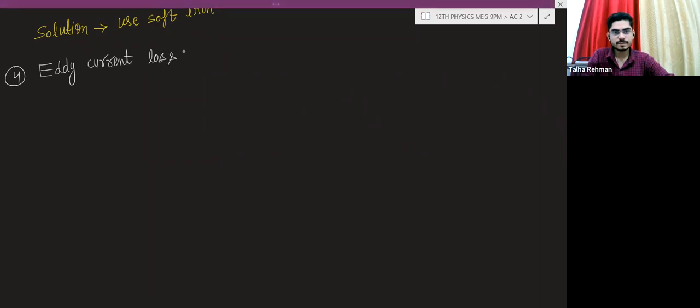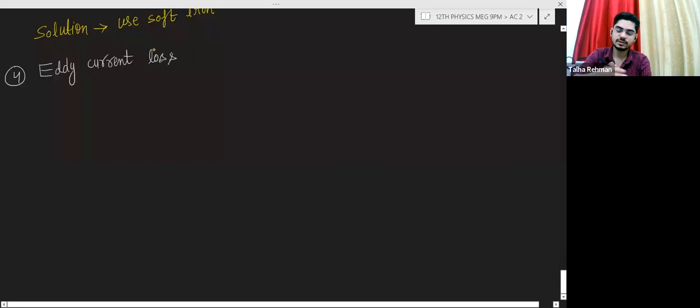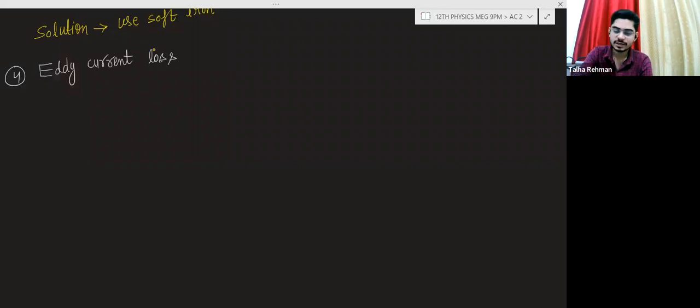So what happens? We know that the current is alternating, so current is changing continuously. Due to that, the magnetic field is changing continuously. Due to that, the magnetic flux is changing continuously. Due to that, there will be induced EMF. Here there are two types of induced EMF.